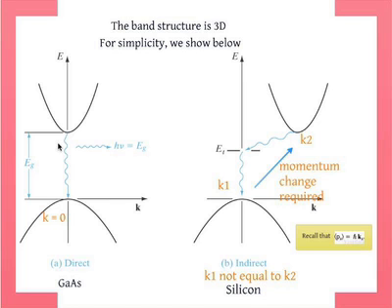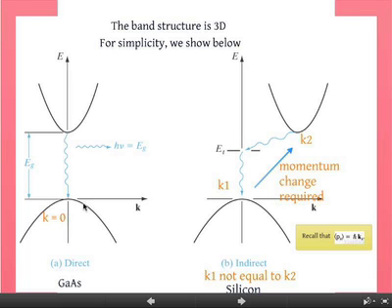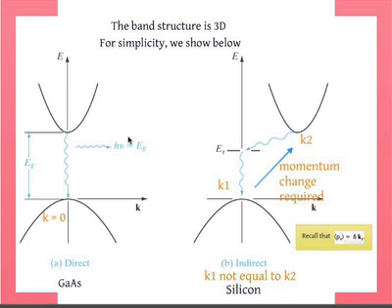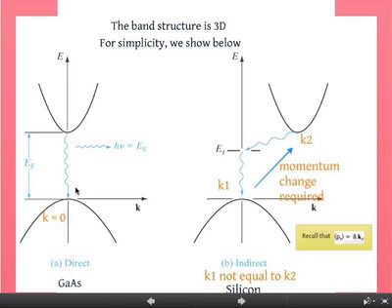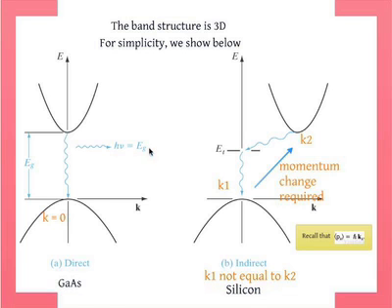This is the reason, actually we'll come to that later, but keep this in mind. If you have an electron which is here, and it gets excited up here by, let's say, light or heat, whatever, if it relaxes back to the valence band, it can release a photon of energy Eg. Okay, we saw that last time. But here, we have a big advantage in this transition because there is no change in momentum. Okay? This turns out to be technologically very important. I'll reiterate that in a second.